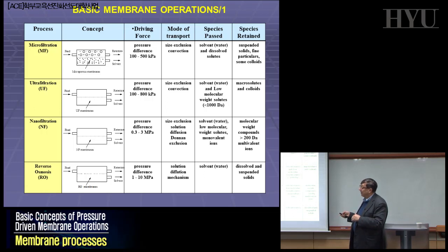In the other case, you can have also some fouling inside the pore, and that, as you will learn, is quite complicated to clean. So you have to introduce a somewhat sophisticated methodology to clean the system when something is going inside. It's much easier to clean the surface, because we can anticipate what makes the most clear difference between any filtration system and membrane technology: that we are never working here in dead-end flow as in normal filtration.